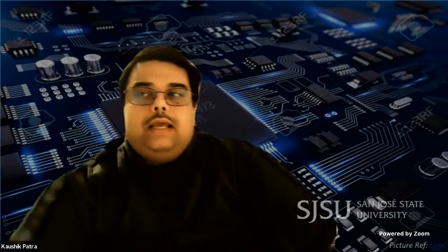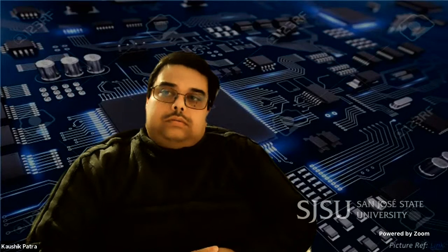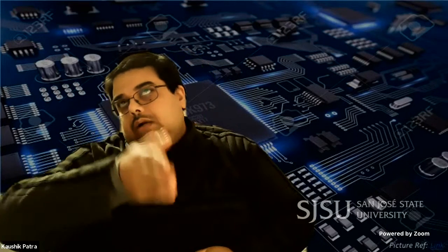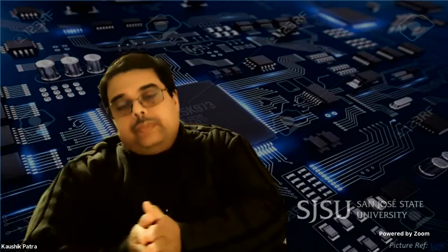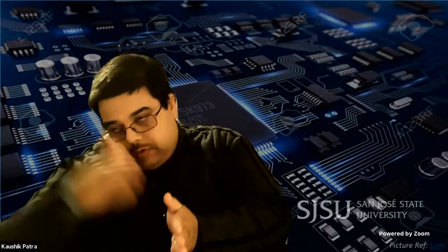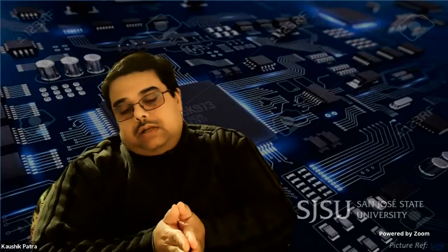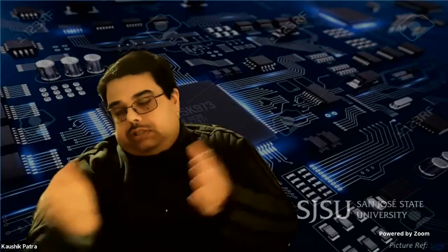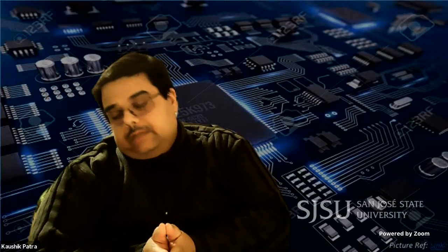If you are uncomfortable with that part, it's basically an unknown logic that will come out of that mux at that point if read is 0. And what I'm saying is that should not affect your overall processor functionality, because read will be 0 only at the write back stage. At that stage, whatever you are reading out doesn't matter in the simulation.